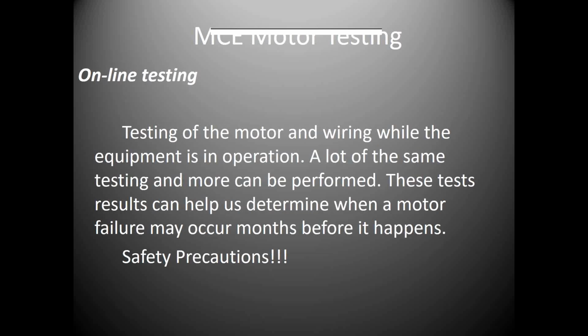If you're testing online while the equipment's running, you can open up your MCC box, or put a plug on the front of your MCC box, and test the motor while it's in operation. Of course, there are some safety precautions for that. We can tell if we've got failures in the motor while it's running, but sometimes those failures could be in the conduit or in the junction box. So we still may have to take the wires off and test the motor at a later date. But again, very good equipment.